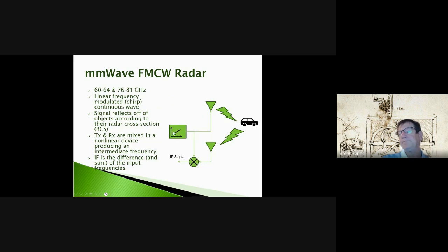And then we'll typically reset and then repeat and reset. So this looks like a little sawtooth wave, except it's not amplitude versus time, it's frequency versus time. But the amplitude is constant. And within this transmission time, we're not sending out a bunch of little pulses, we're sending out one continuous wave, but that is constantly changing frequency.